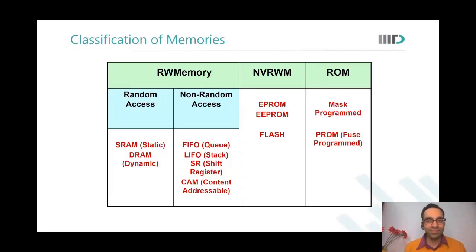So when we are using a frequency conversion, like when there is a change in frequency from one system to another, we are using them maybe. Okay, good. So that is definitely one application of a FIFO, where we transition from one frequency island to another frequency island. Very good. Where else?